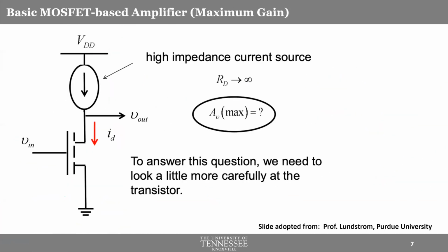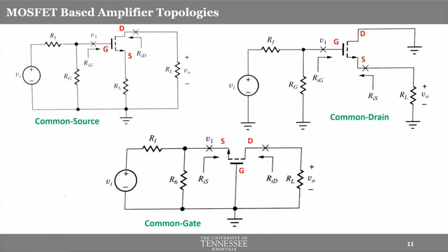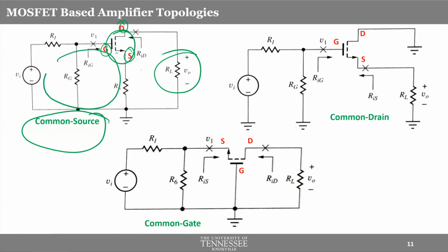And let's go back to that particular slide where we have other topologies as well. Let's look at the common source topology now. So this is our transistor that we are dealing with. This is the resistance that we talked about, just being shown in a different way because this is taken from another textbook, not the textbook that we usually follow. But anyways, so we have gate, drain, and source, and you might notice that source is part of the input circuitry.